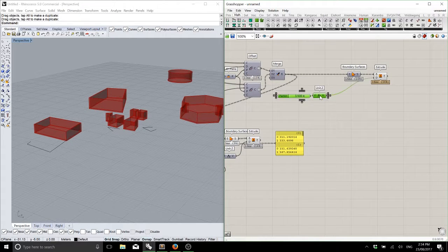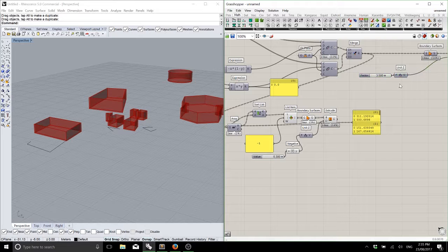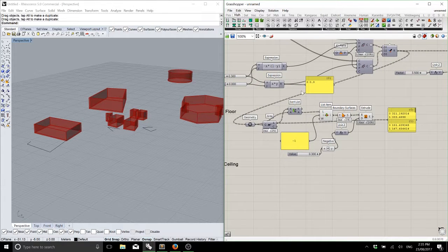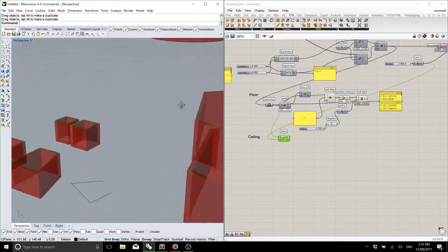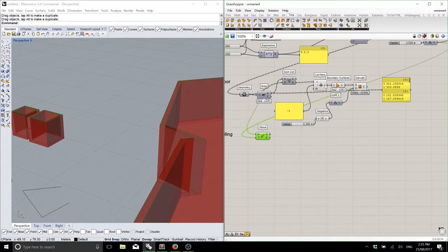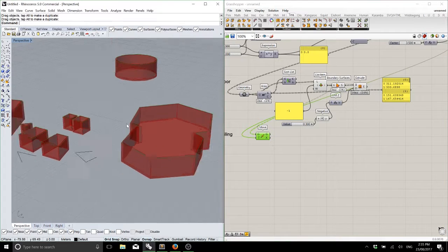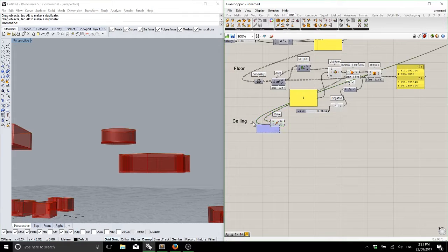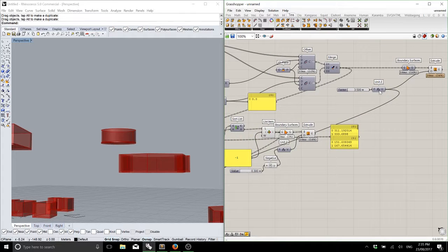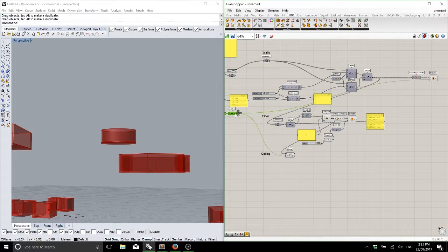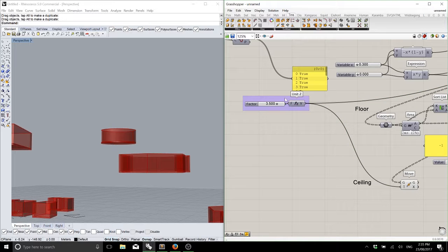So here's the height of the wall. It's already a vector, so we're going to utilize this variable to move this floor curve. So we're going to transform our floor curve up using that z vector. There it is sitting there. It's a move, and we're just utilizing the height. So I'll keep that over here and I'll group that and call that room height.